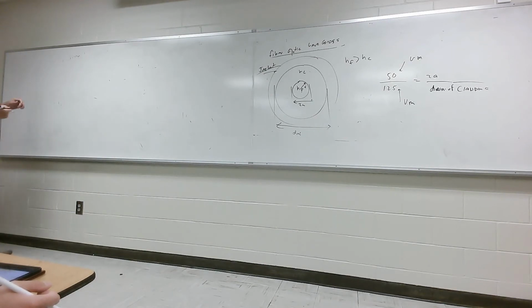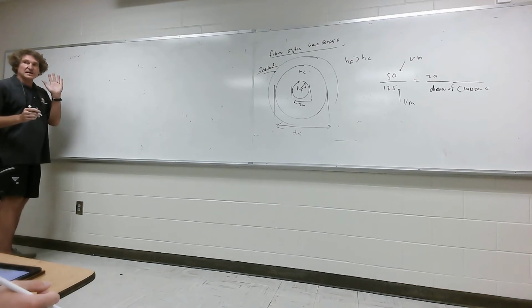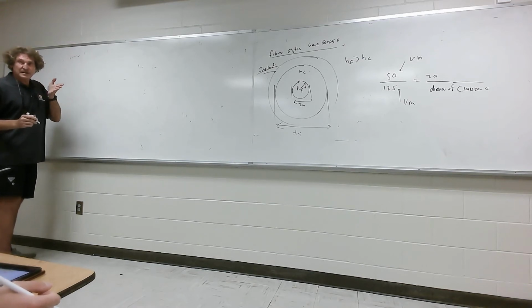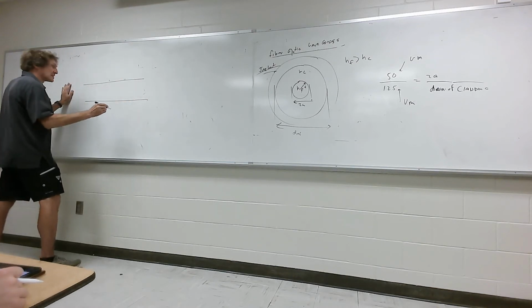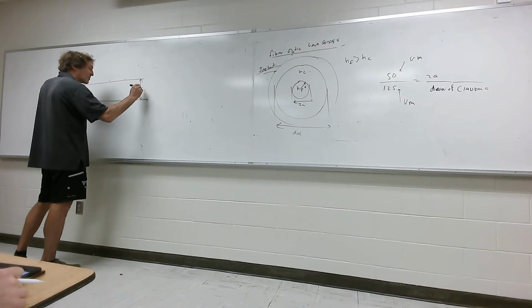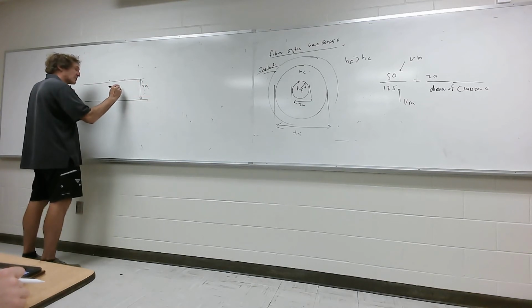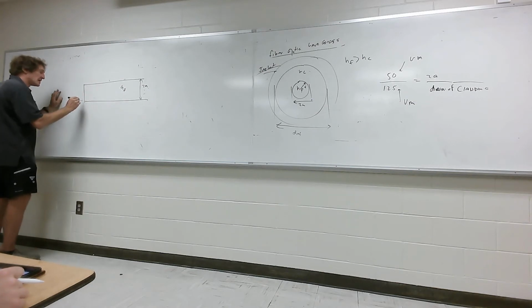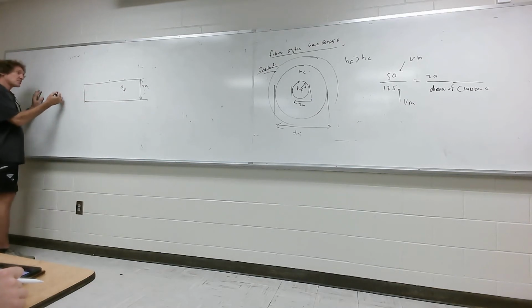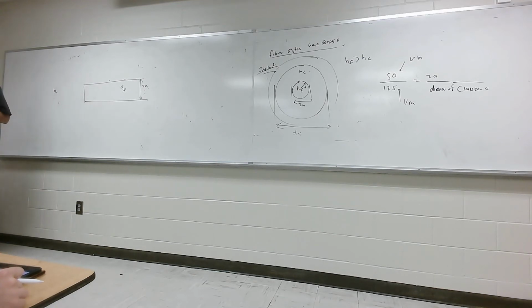When we look at this, I'm going to cut the wire down the middle and look at it lengthwise. Here we have the actual core, with dimension 2a. They call it the fiber core, and it has an index of refraction n_f. Then you have an external light source, with an index of refraction n_0. Usually if we're talking about air, the index of refraction would be 1. Do y'all follow me on that? Because n is just the square root of epsilon relative, and epsilon relative of air is 1.